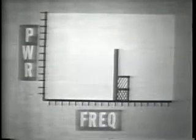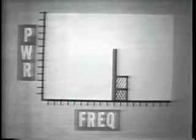If we eliminate one sideband, we would narrow the required frequency spectrum by 1/2. And we'd still have the same intelligence in the remaining sideband. And by putting the power from the removed sideband into the remaining sideband, total sideband power is restored and is contained in just one of the sidebands. Well, so far, the sideband energy has only been rearranged with no resulting power gain in the information being transmitted. However, putting the carrier power into the remaining sideband would boost the sideband power tremendously. Now, all of the transmitter power is located in one sideband.